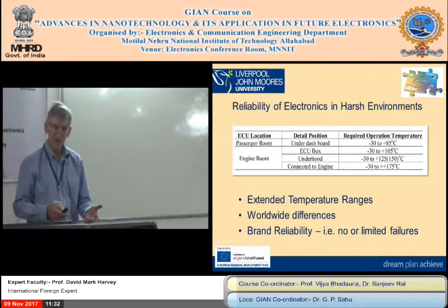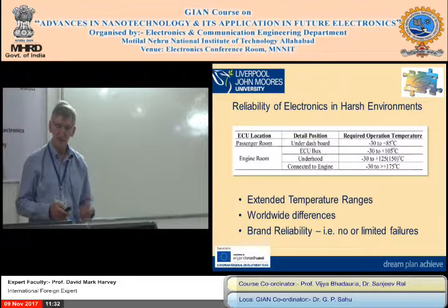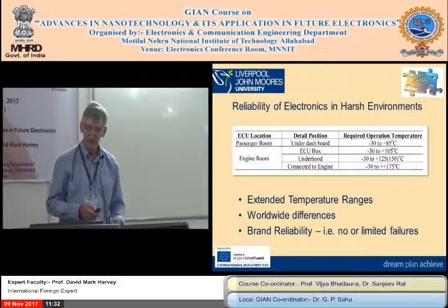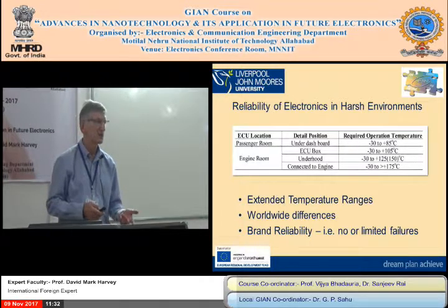So we've said this again, what's the lifetime? Is it 10 years? How long will the engine control unit, or the ECU, last? And we're looking at the solder joints because they are generally the weakest link. They will break first.